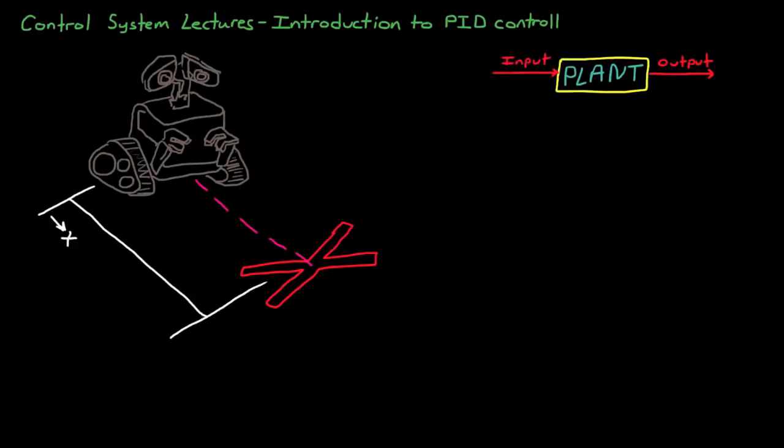Open loop commanding is perfectly fine for systems that don't change much or where accuracy isn't as important. However, what if there's some dirt in one of the wheels and the robot veers off to the side? Or if the robot's slightly faster than you had predicted? In both of these cases, the robot won't stop on the red X because it has no way of compensating for these errors and making adjustments on its own.